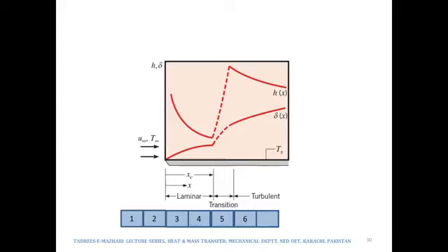Because if the flow is entirely laminar or entirely turbulent, there would not be this transition, and it would be either this decrease taking place all over the length of the plate, or it would be this decrease taking place over the entire length. So therefore, where would maximum value of H be? It would be on the very first heater.